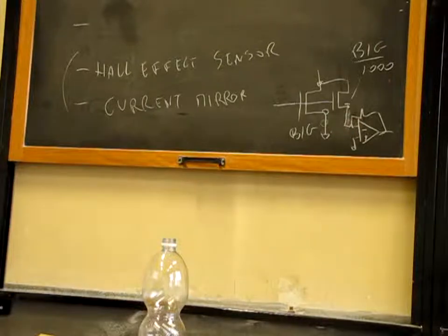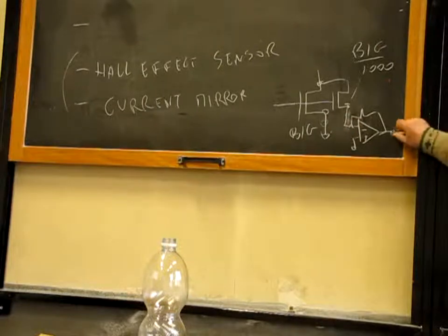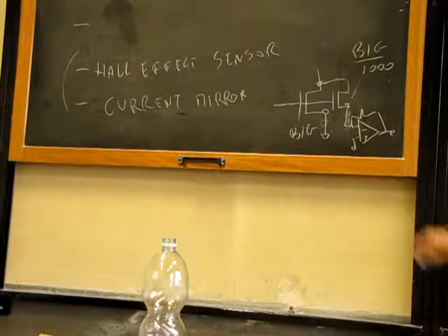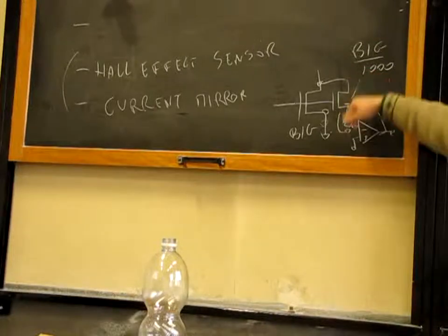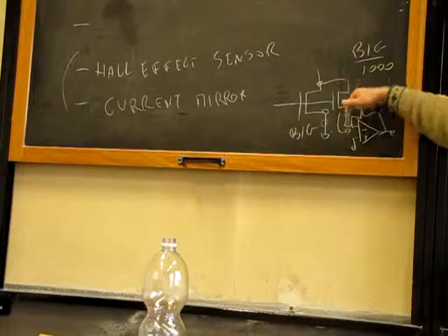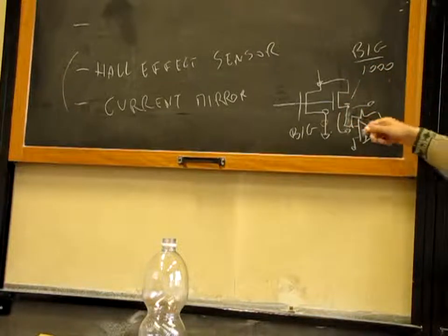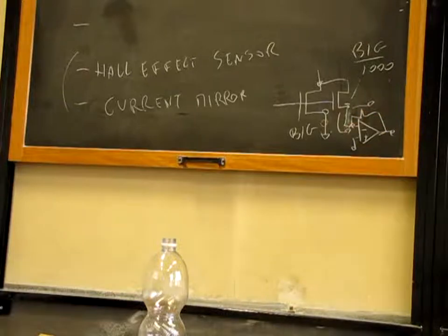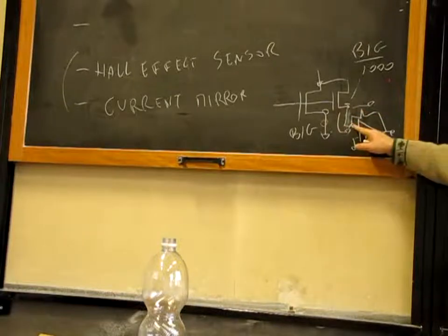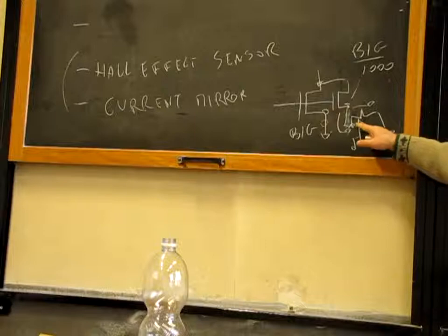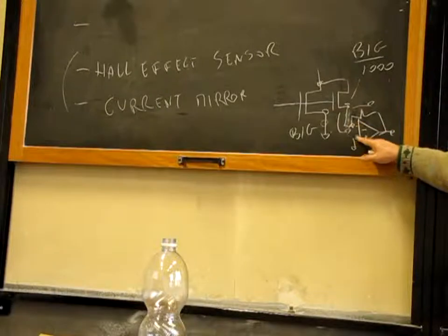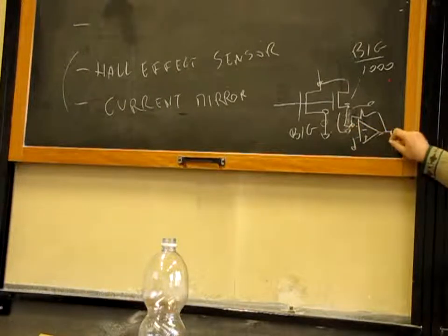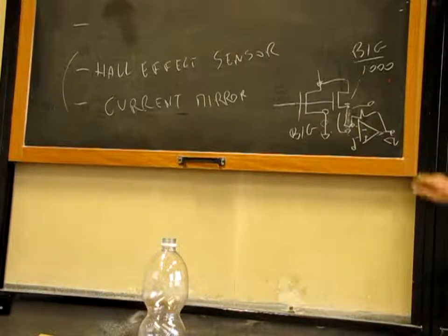And then this fast op-amp had to give you an output voltage that is negative, because if the voltage goes in, the current goes down like this, flows through the feedback resistor, going to the right, and the left-hand side of the resistor is at 0 volts, because the inverting input follows the non-inverting input. Here you have 0 volts, here you have a negative voltage. So you have a negative voltage, less than 0 volts, here at the output.